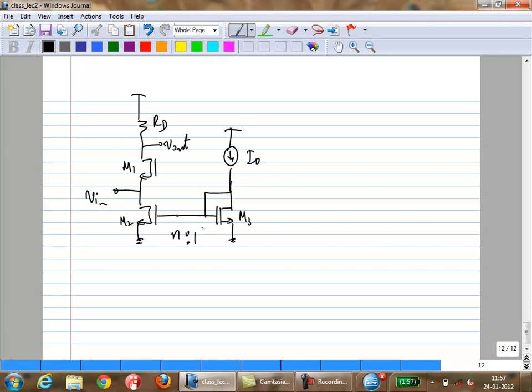Okay. What can you do about M3? So one thing you can do, which people often do, is to add a capacitor here. What happens? This capacitor shunts any noise from M3 to ground. Okay? So that noise from M3 gets shunted to ground and it doesn't get multiplied up. Okay? This is something you can do to get rid of M3 noise.